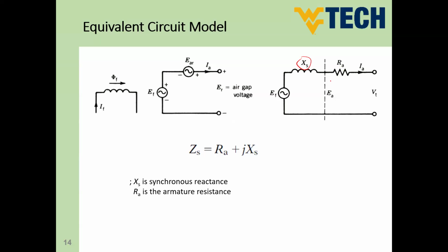As you know, guys, we will discuss the three-phase machine. So this equivalent circuit here, guys, is a single line diagram, which means we have this for the three phases, phase A, phase B, and phase C. However, because we have three identical phases, all of the time we will consider that we have one circuit, which is the single line diagram.